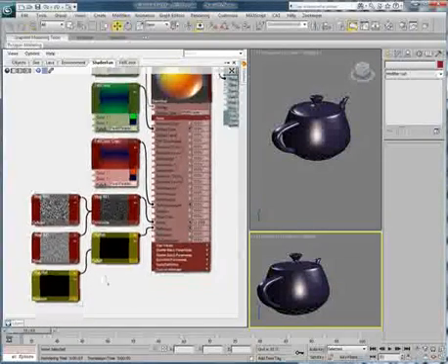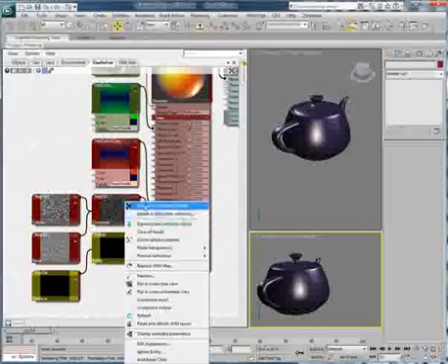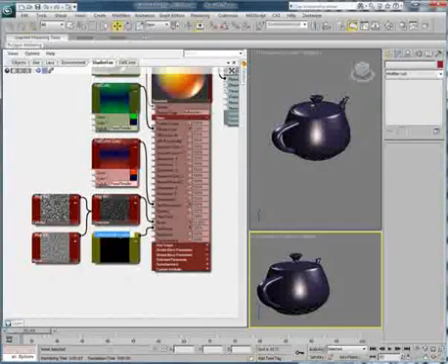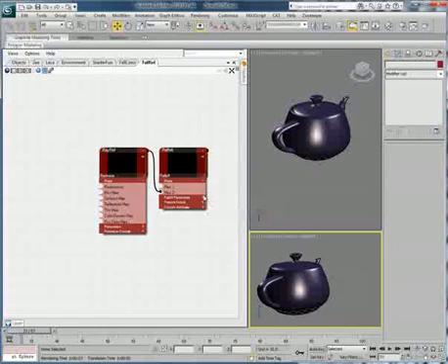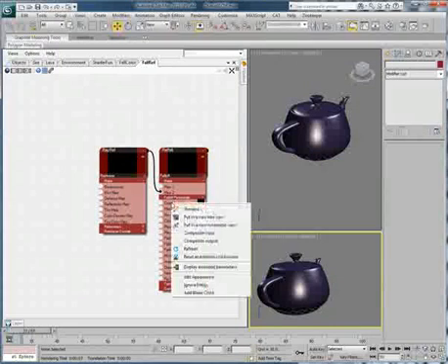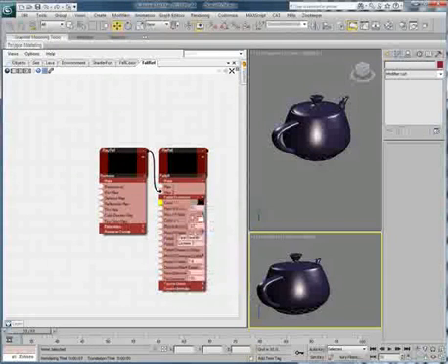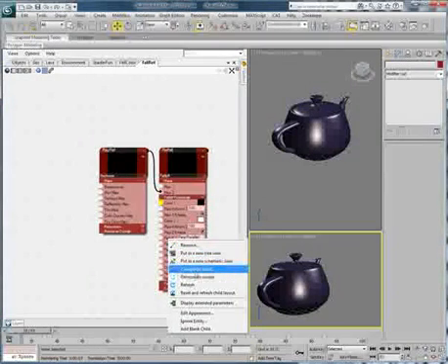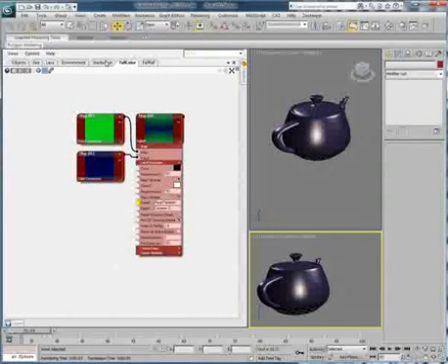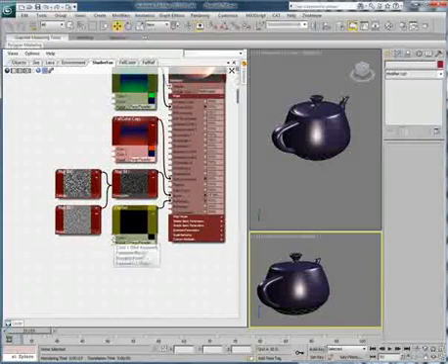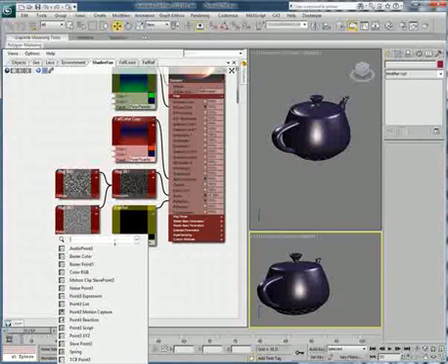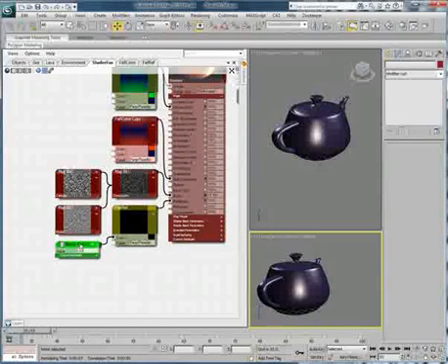And a lot of times I would do the same thing with a fall off and a reflection. So I can do the same thing here and just kind of group that and call this fall ref, and hop in and adjust different parameters in here that I might want to show up. So map 1, map 2, maybe in that map 1 I may want to expose this color, so in case I want to pipe something else into that map 1 for the reflection, again probably the fall off, so I'll say make that a composite input, and I'll hop back over here and you can see those things are present. So if this reflection fall off, maybe I need to pipe in some sort of controller for that color, a Bezier color or something like that.